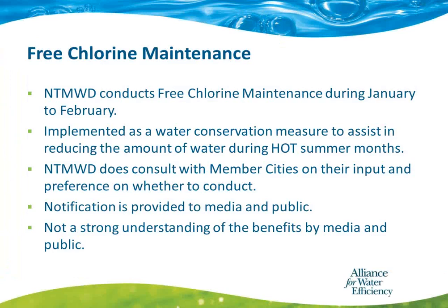And in regards to responding to drought, we also have to maintain, as Bill had discussed, water quality, that chlorine residual, to maintain that safe water for use. The district does implement a common strategy that is recommended by the state of Texas, that you conduct a free chlorine maintenance. Our chlorine residual is in the form of a chlorine and an ammonia molecule, chloramine, so that the chlorine will have a longer lasting effect out in the distribution system.